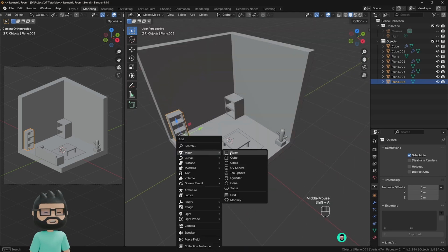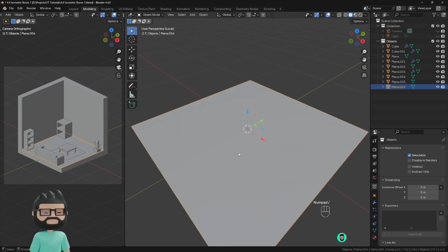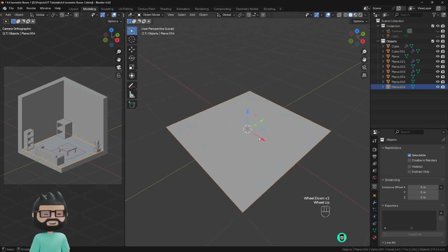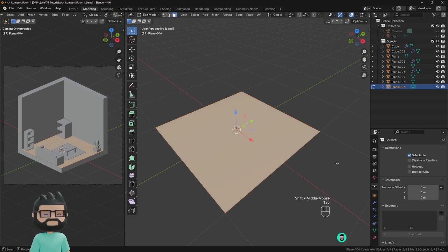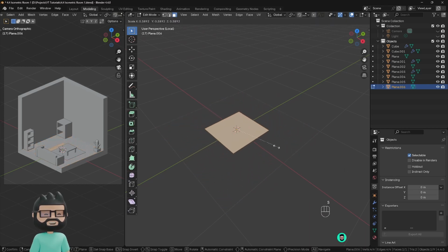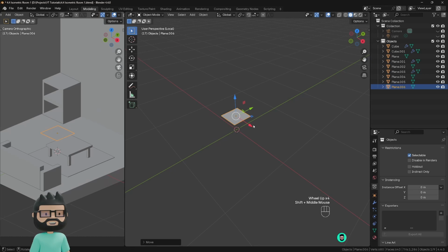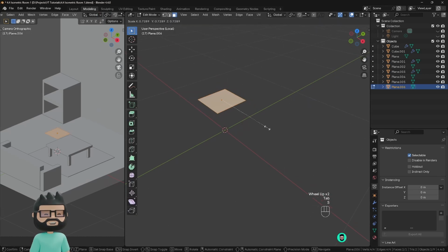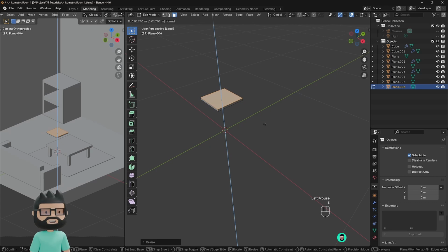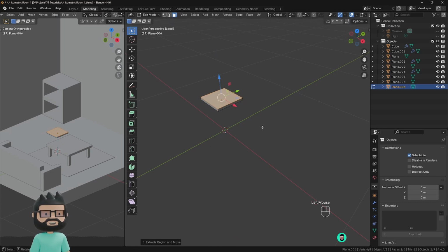Next, let's add some chairs, simple chairs. Press Shift A, Mesh, and let's add a plane. Press / to go into the isolated or local view. Press Tab to go into edit mode, S to scale, scale it inwards about this much and move it up. You can also see the whole scene from here and zoom in as well if you want to. Tab to edit mode, S to scale again, and E to extrude a little upwards. Now we actually want a chair with 4 legs, so it would have been better if we have just taken the table and duplicated it to make the chair legs.